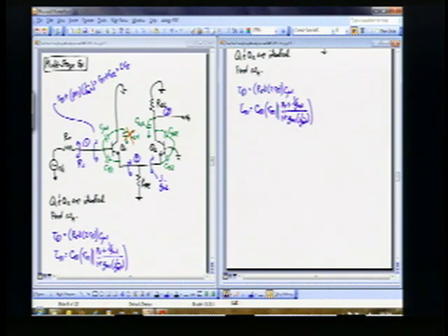But see, it's not so bad. If you have that expression memorized, you can just write it down. If you don't have that expression memorized, then you're going to have to draw out the hybrid pi model and do a bunch of things to get that time constant. Now, there's one thing I do want to tell you, though, is that oftentimes this is a neglectable capacitor. Can anyone tell me why I'm saying that's a capacitor you can probably neglect oftentimes? Not all the time, and in fact in this problem you can't neglect it.